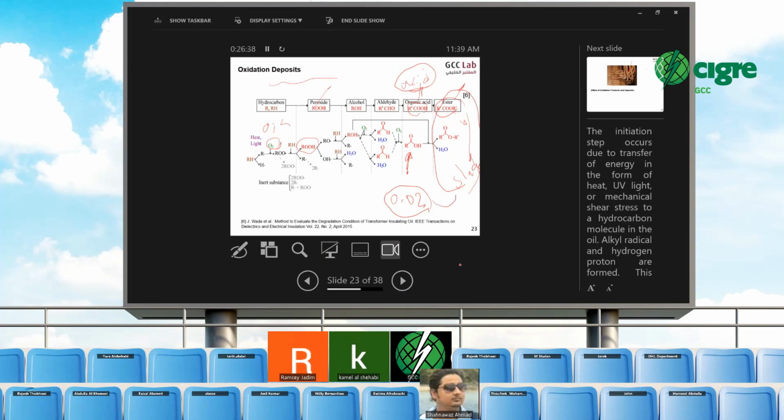If some acid went to sludge, you cannot see your acid. You see just a little acid, and also some peroxide. You have 0.02 acid, but extremely high peroxide. That means the reaction is heading toward more acids. This reaction does not take 1 minute or 2 minutes. It takes maybe 3, 4, 5 years. It is a very, very slow reaction, but in the future it can happen.